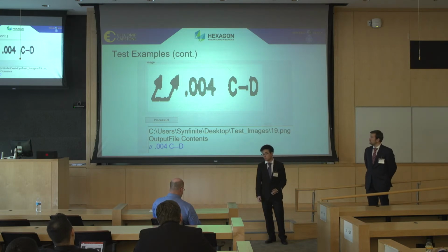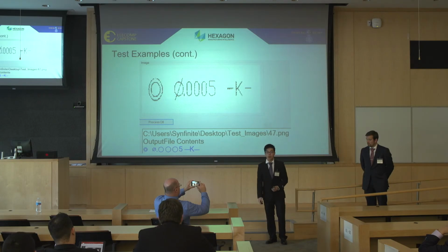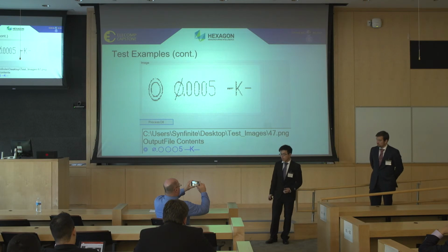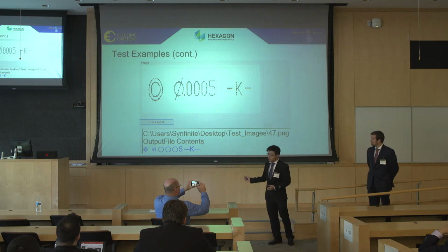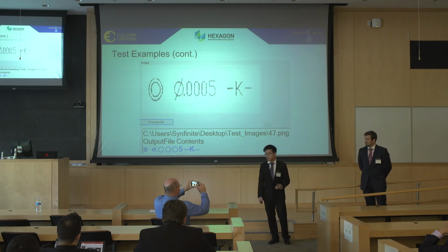As in this example, even after pre-processing, the characters are really blocky and have low quality. When the quality is low, Tesseract will sometimes mistake one character for another. For example, it might recognize the period here as a comma, or the letter O for the number 0. In this specific instance, Tesseract was not able to recognize all the characters correctly. This next example shows how a character can get misrecognized. The zeros in this column got interpreted by Tesseract as the GD&T symbol for roundness, and this is not what we want.